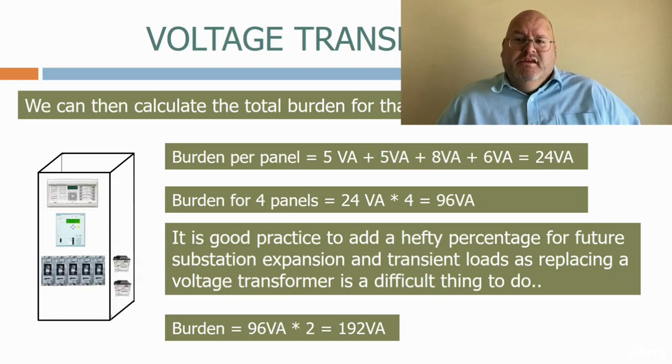In older systems, the voltage transformers were a lot larger, as the older electromechanical relays had a large burden, which drew a large amount of power from the VT. Modern microprocessor relays draw a very low burden from the system, and the VT sizes can be significantly reduced.